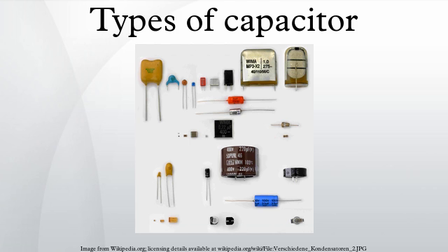The aging process of Class II ceramic capacitors may be reversed by heating the component above the Curie point. Class I ceramic capacitors and film capacitors do not have ferroelectric-related aging. Environmental influences such as higher temperature, high humidity and mechanical stress can, over a longer period, lead to a small irreversible change in the capacitance value, sometimes called aging too.